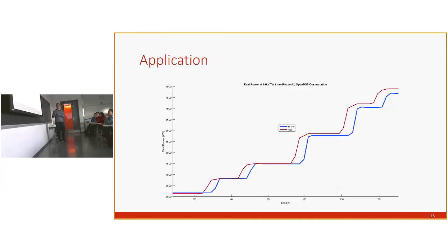So here you'll see the Reg D signal coming in and the power exchanged on the tie line. Reg D in red, tie line in blue. You'll see that the Reg D signal comes in first, and after about a 4-second delay, it varies between simulations, usually between 4.3 and 4.7 seconds, you see the microgrid respond. And we see that for this, this was just manually inputting different values to test an increasing ramp. We see that the microgrid does follow the Reg D signal as it should.